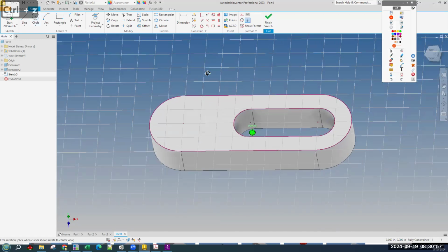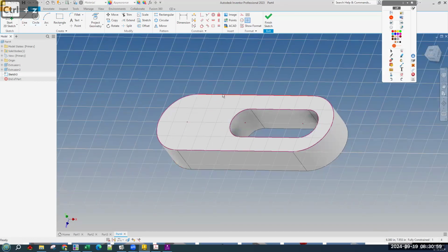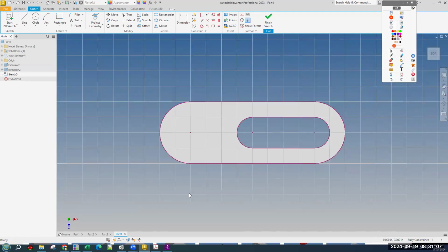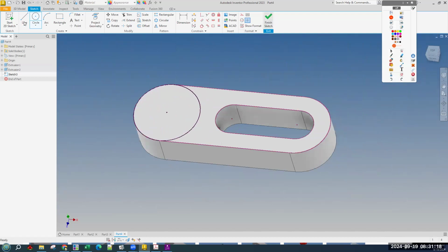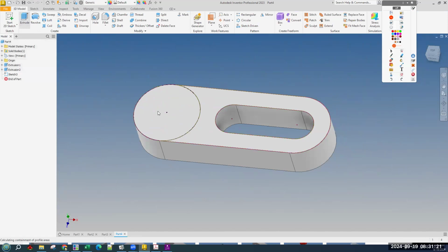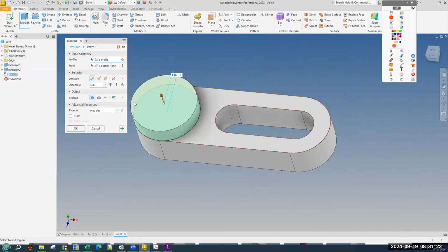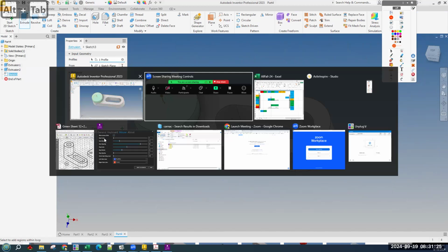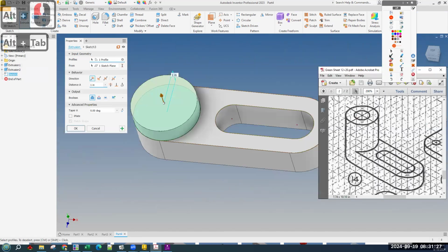So all I did was put a sketch on this top, and because we have that setting, auto project edges and for sketch creation edit, we get this snap, which is what we've been getting the whole time. But with a circle, same center point here, first click and second click somewhere on the edge over there, finish sketch, extrude, choose this thing, and we want to extrude it up however far past what we already have.